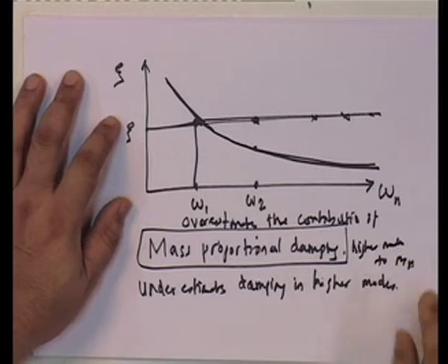Understand that if you underestimate damping, what are you doing? Lower damping always increases the response, except, remember, in transmissibility, where actually you want damping. But let us not go there, that is a design. Let us take a structure. A structure is being subjected to arbitrary loading. I assume damping to be mass proportional. If I assume damping to be mass proportional, I can only fix it in one mode, and that typically is the fundamental mode, because that has the largest value.